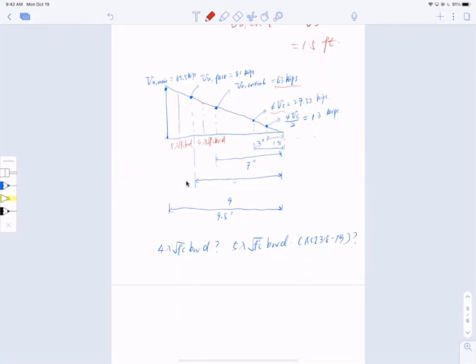Essentially, I'm just going to do a spoiler here. Lower than this number right here, this region, let me label it 1, stirrups free, or at least provide some minimum. In this region here, between half phi VC and phi VC, we need to provide stirrups as well, Av min, and also maximum spacing applies.